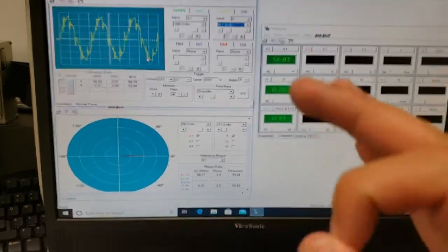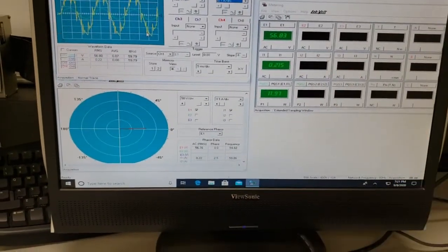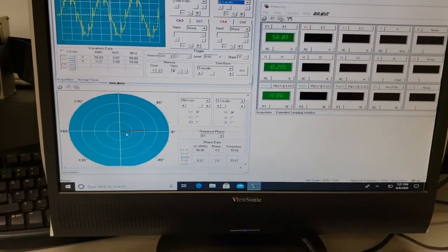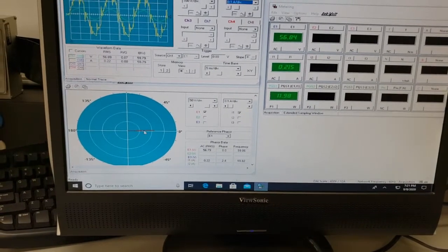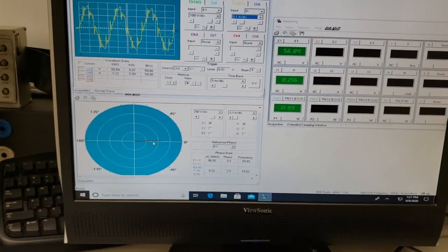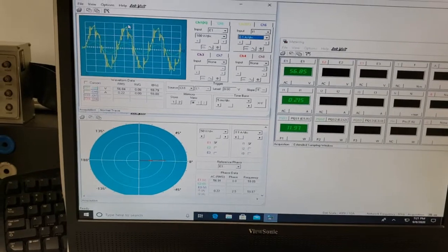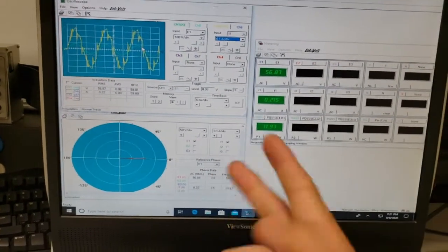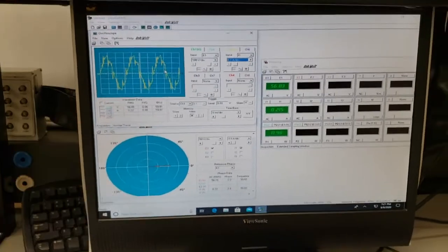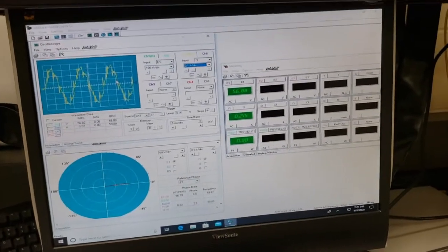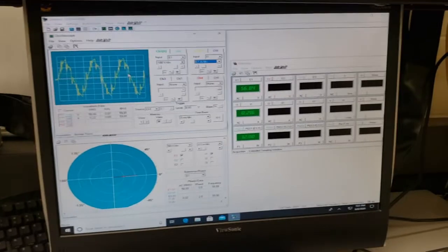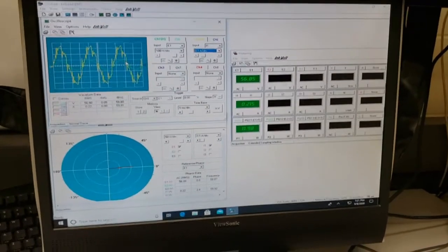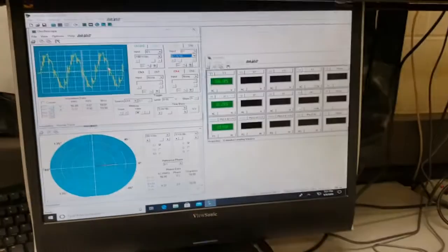But what you should notice, and this is the main cancellation that occurs, is that indeed, look, the current and voltage waveforms are almost in phase with each other. And you can also see that here the peaks line up almost exactly because of that equal and opposite admittance that the inductor and the capacitor provide the circuit. So anyways, that's part A. I hope I didn't miss anything, but yeah, all right.